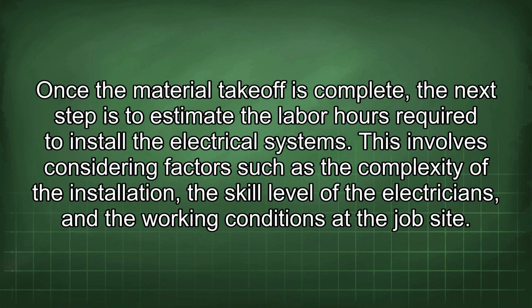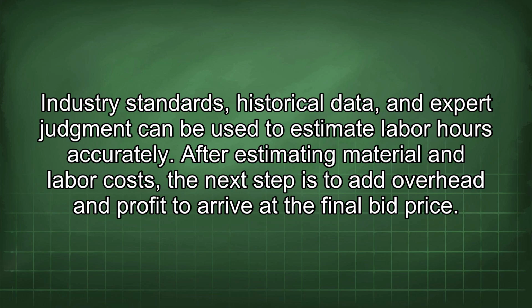Once the material takeoff is complete, the next step is to estimate the labor hours required to install the electrical systems. This involves considering factors such as the complexity of the installation, the skill level of the electricians, and the working conditions at the job site. Industry standards, historical data, and expert judgment can be used to estimate labor hours accurately.